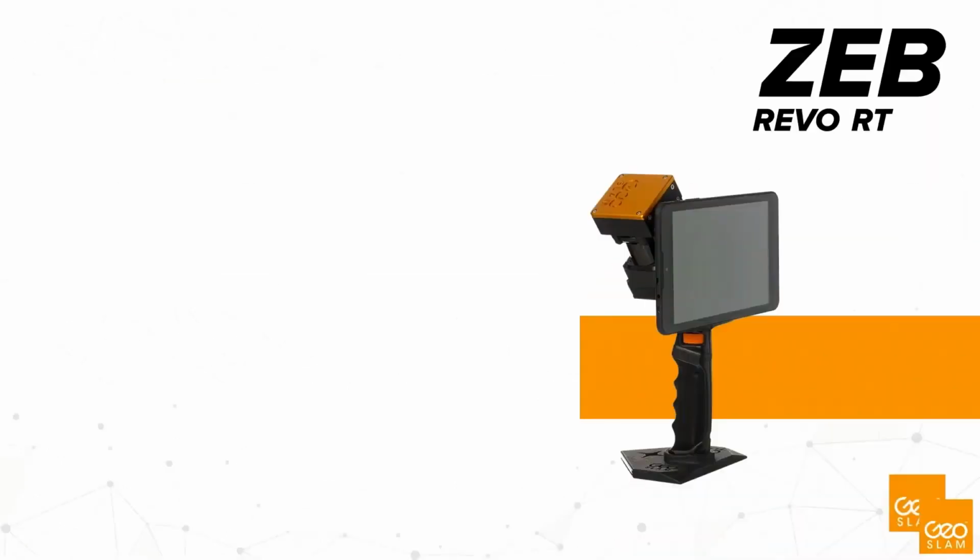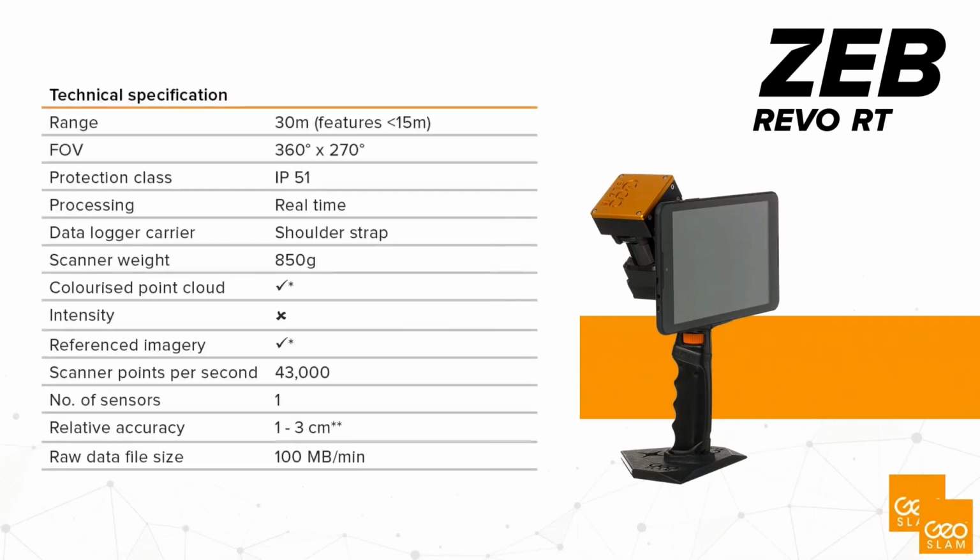The ZEB Revo RT real time. So this is one of our most popular scanners. Again, a 30-meter range, but this is a real-time processing unit. As you can see on the back of that unit, there's a tablet. And on that tablet, that will display the point cloud in real time as you're walking through. So this is really, really useful to understanding exactly what you're capturing. As you're walking around, every step you take will be more and more data being displayed at that time on your tablet or phone.